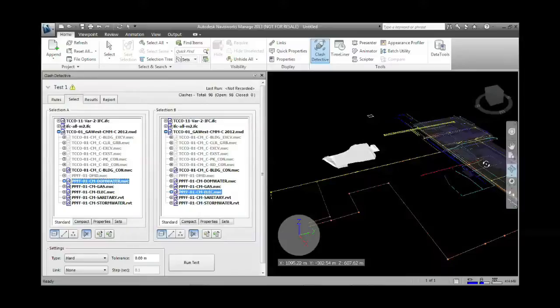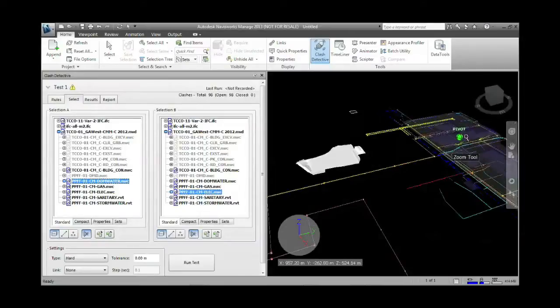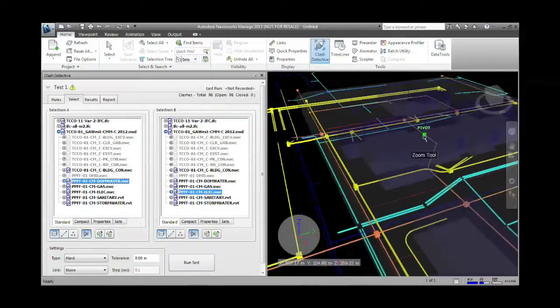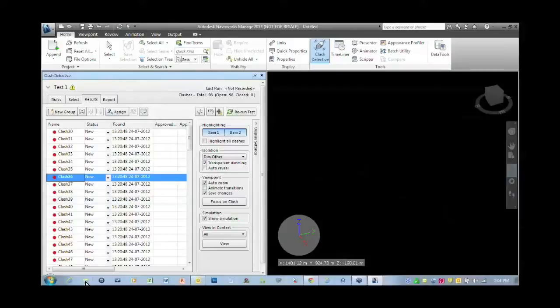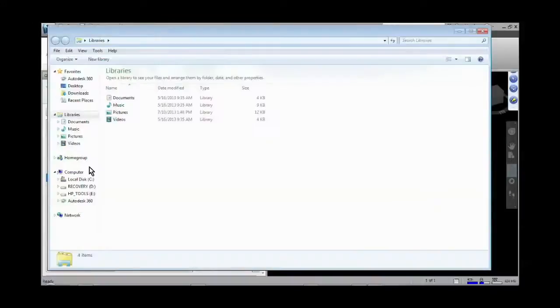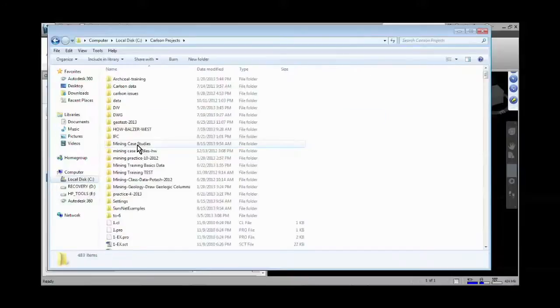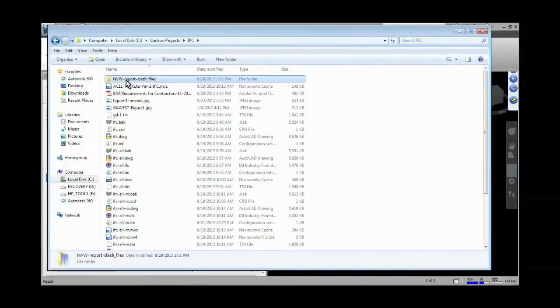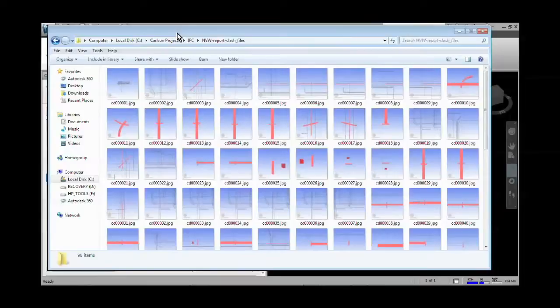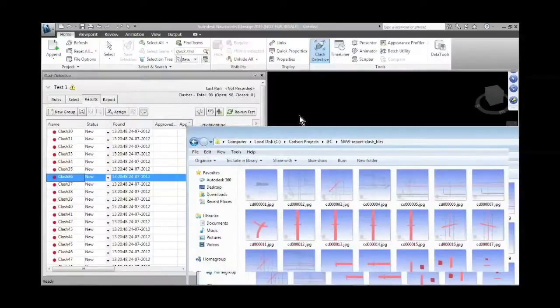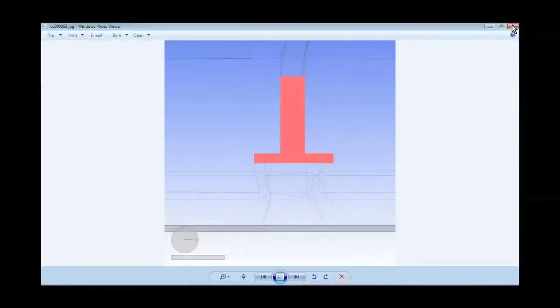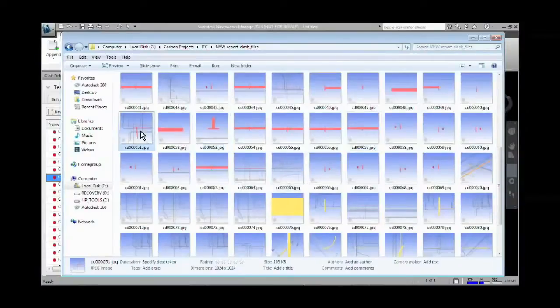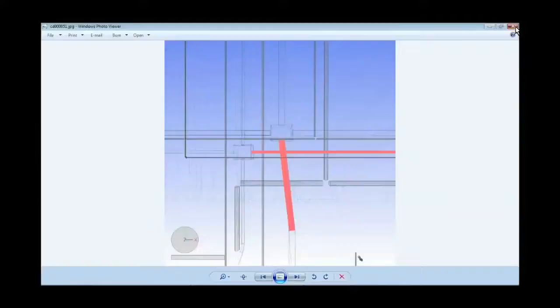This is a huge complex with many, many buildings on it. You can kind of see how many buildings are in here, right? And the idea then would be to look at clashes and things like that. So by running some tests, you can find out what utilities are clashing, which ones are not. And again, I'll show you what the output would look like. It would be something like this, where every one of those clashes that you just saw me looking at, they will identify those graphically for the client or for whomever is doing the BIM analysis. You see that? It's finding every single conflict and clash that could be occurring in the file in 3 dimensions.